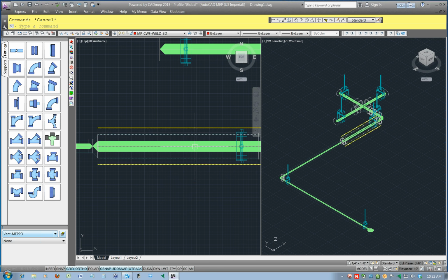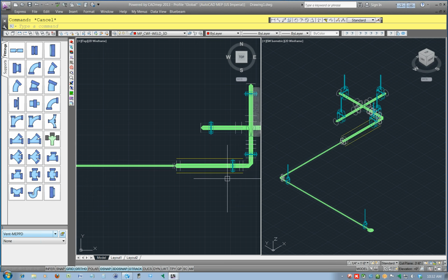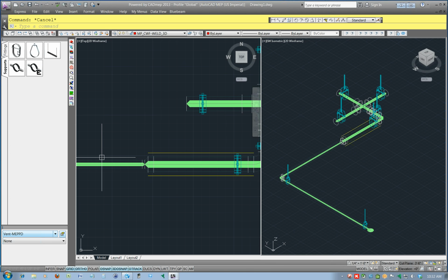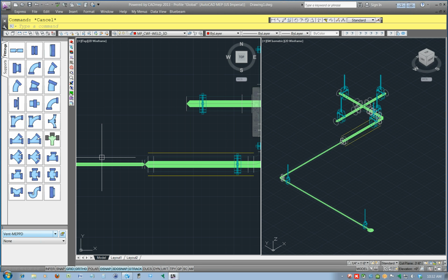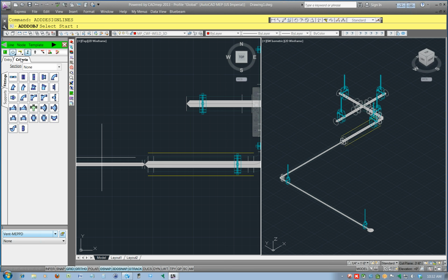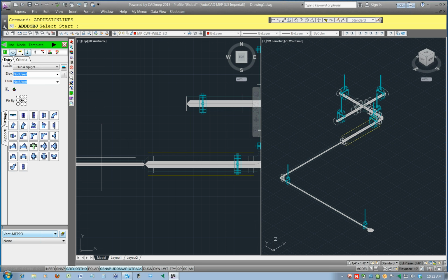It's showing you're lagging. Okay. No, it's not oversizing the hangers though. It doesn't look like it. Right, because the hangers filled in prior to us. It won't change your hangers automatically. If you have insulation on while you're drawing, will it oversize the hangers then? Yeah, if you're in design line, there should be an option in here to tell it to use insulation.